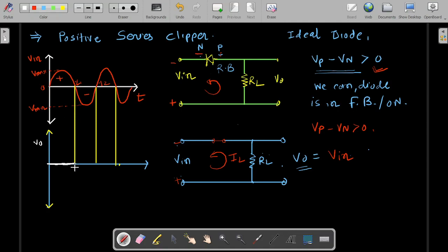So in our waveform, whatever input half cycle is there, the negative half, that is going to be followed at the output. Here we'll get the same output, the V max negative value. So the output follows the input; input equals output. For this circuit, the positive part of the input waveform is clipped, and the negative part is not clipped, it is as it is, followed by the input.